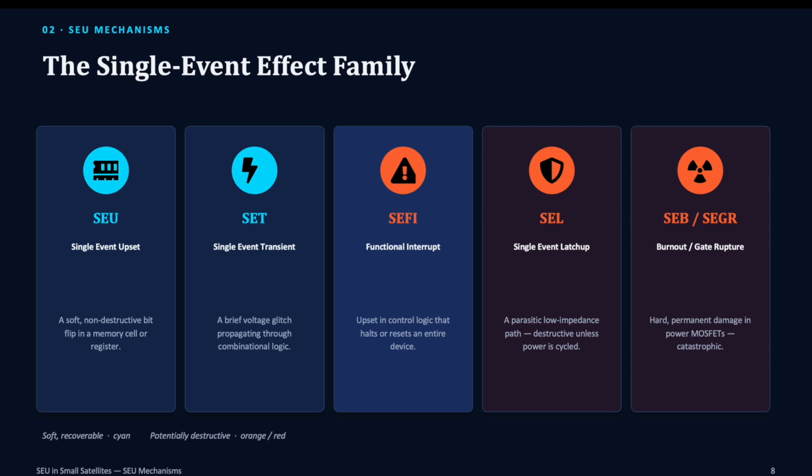And the potentially destructive ones are single event latch-ups, caused by particle strikes turning on unintended parasitic thyristors and creating low impedance short circuits between the power and the ground, and single event burnout or single event gate rupture, which triggers catastrophic short circuits causing permanent physical damage. It is this burnout and gate rupture that is the most permanently damaging type of effect.